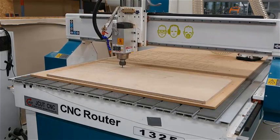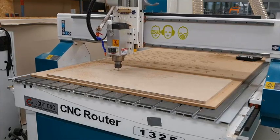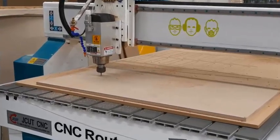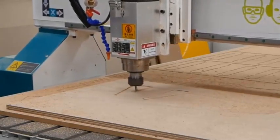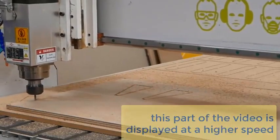We found that on this machine we could increase the speed to 4000 millimeters per minute with a theoretical machining time of 6.5 minutes. In real life that proved to be 8.5 minutes, as the machine cannot always achieve the prescribed speed.